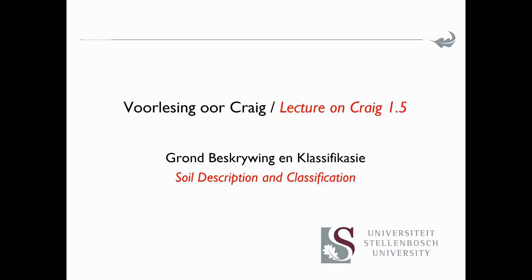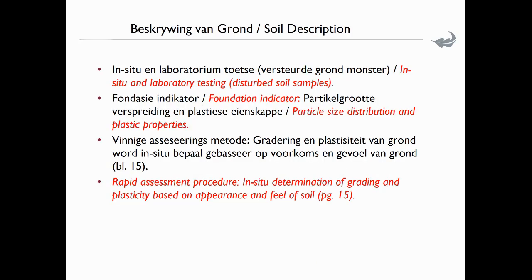So the lecture is on Craig 1.5, and it will cover soil description and the classification of soils. Soil description, you can either do it in situ, in other words in the field, or through laboratory testing on disturbed soil samples. We also use undisturbed soil samples sometimes for certain of our tests. Then in the lab, we also do foundation indicator tests, which is basically the particle size distribution and the plastic properties, which is what we discussed in the previous lecture.